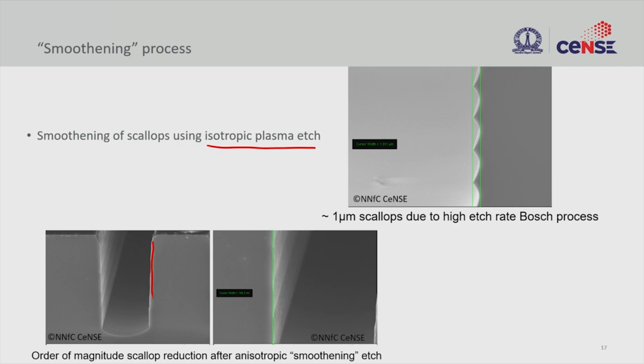It's completely gone. It's a very smooth etch process, right. So by using a combination of isotropic and anisotropic, we were able to etch very deep trenches without having this isotropic artifact.